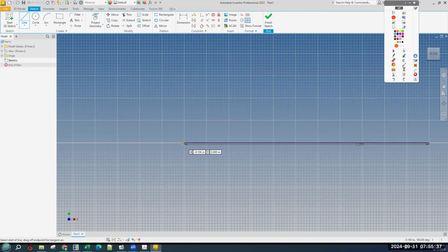If you click sort of close to it, it might look right, but it won't let you extrude if the shape is not what's called a closed loop. If it's not an enclosed shape, it won't know what to extrude. So first click there. Another thing, you need to make sure it snaps to vertical. You can see right next to my cursor, that little icon pops up, and it's telling you that it's going to constrain it to vertical.